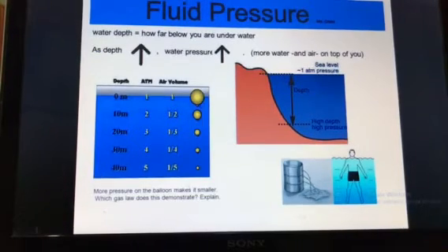Okay, so an easier equation to remember and apply for the pressure difference between any two points in the same fluid under hydrostatic condition is that the pressure below is equal to pressure above plus rho g h, where h is the difference between these two points.